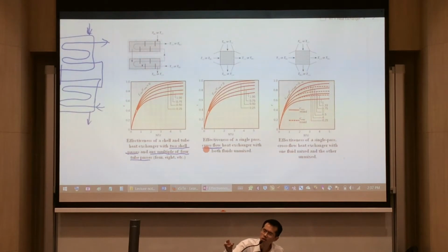Why is it that when they are mixed together, ice Milo, it cannot be a heat exchanger? Because with a heat exchanger, while it comes together and exchanges heat, we actually want to recover that fluid for circulation. So once it's mixed together, you can't really recover that hot and cold fluid for recirculation. Once ice Milo is mixed together, can you extract the ice anymore? You cannot. So that's not a heat exchanger. So when you have cross flow, you need to ask yourself the following question.